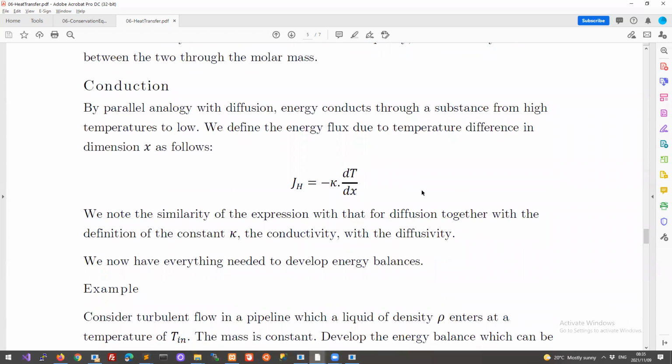And we have now the conductivity, or conduction flux. We can see here, this is dT/dx. Temperature we know is a measurable thing, and this x is the measurement in a spatial dimension, so this is on the order of meters. This is measurable. We can define the space. We can define a distance down a space. So this gradient is in terms of things we can easily identify and imagine.